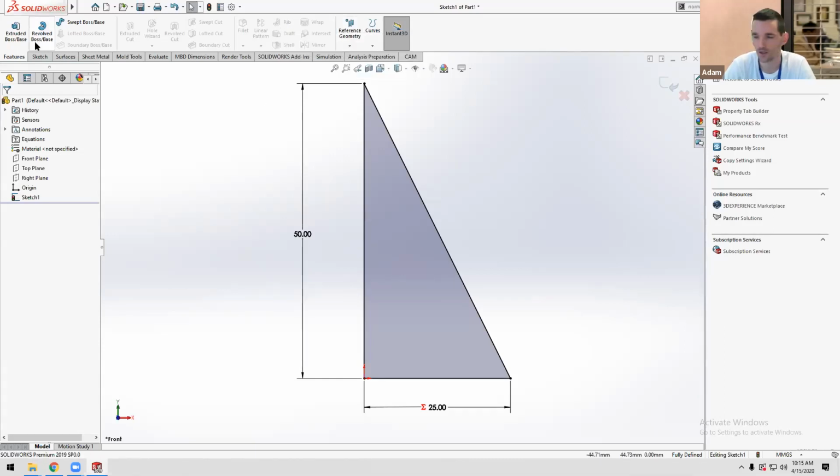Okay, and this is the order of operations that you should do to make a model. You should make all of your positive shapes, then cut all of your negative shapes, then round off your edges, in that order, because it's the most robust way to make your model, meaning that if you go make changes later, it's not going to ruin the features that you've made previously.